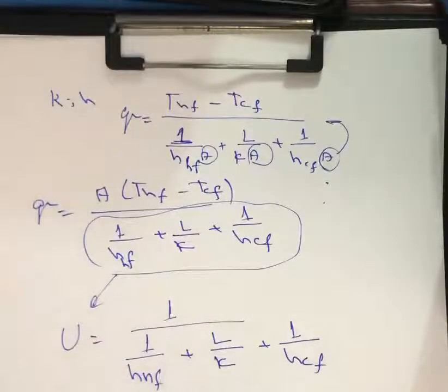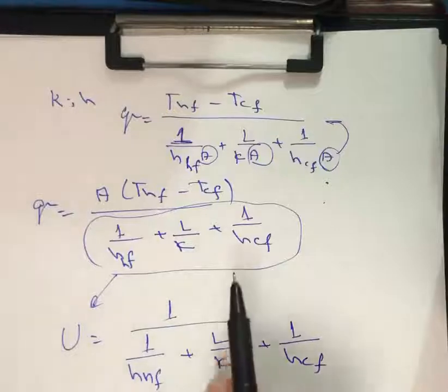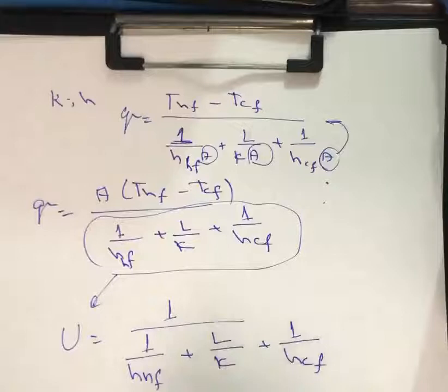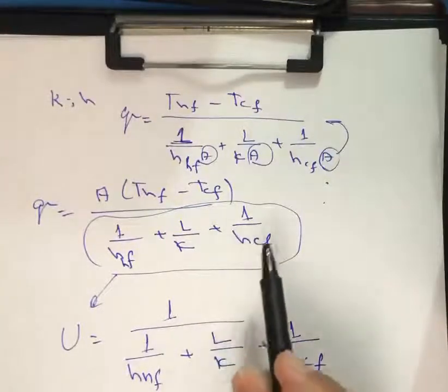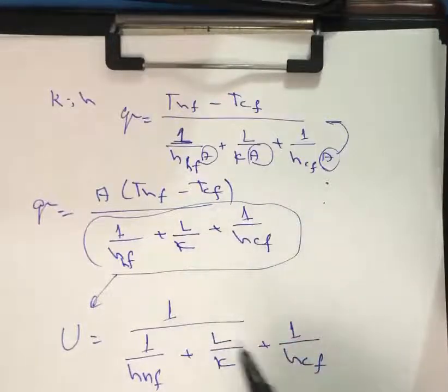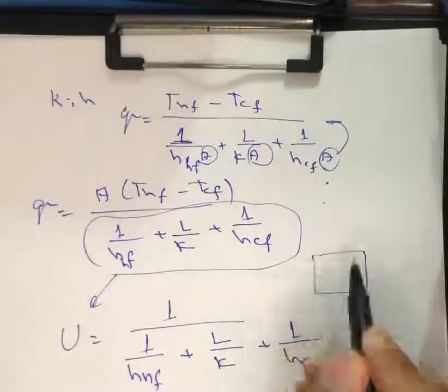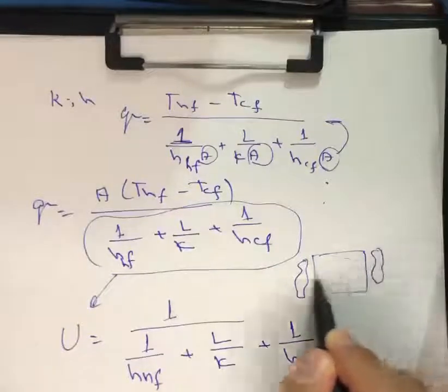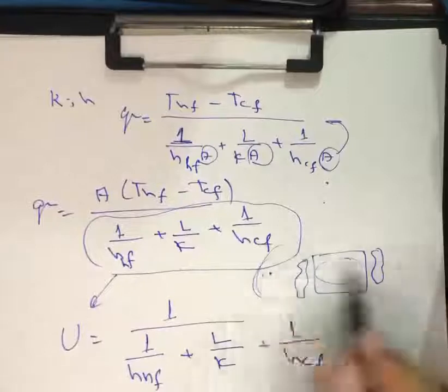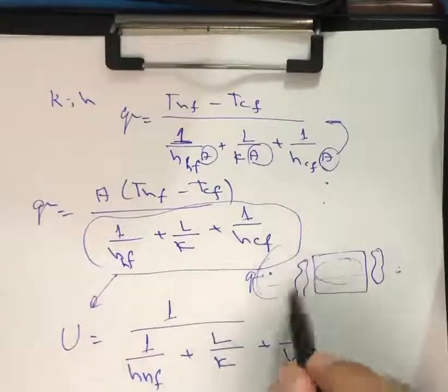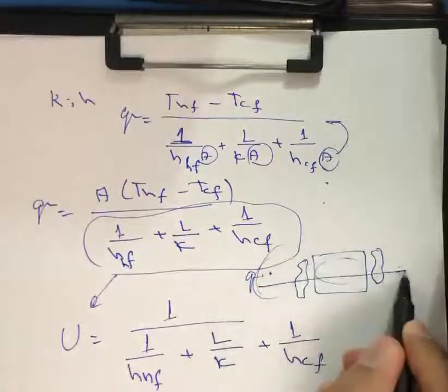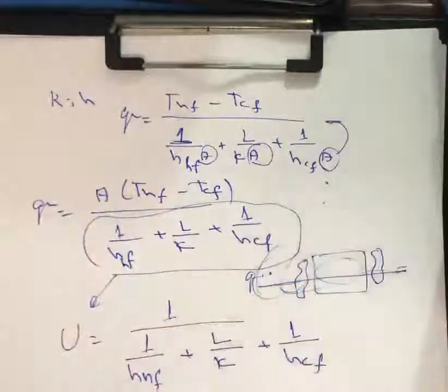In this lecture, we illustrated the derivation of the heat conduction equation and the assumptions we can make in order to simplify the equation as much as possible. After that, we included the concept of thermal resistance and how we can calculate the heat transfer through a plane wall and through a composite wall. Besides that, we considered a solid material with a fluid attached to it, a hot and a cold fluid environment, and how to calculate the heat transfer. The most important assumption we make is that the heat transfer through the wall and through the convection remains the same, in order to make the simplification as easy as possible. I hope it is clear.